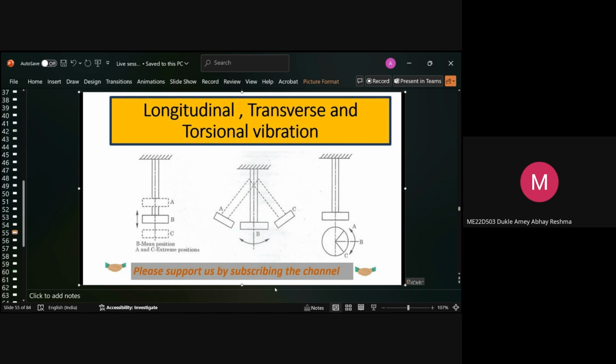When there is a pulling and a change in length, as we saw in the previous question on the stress and strain relation, then it is the longitudinal vibration. When the force is applied and there is a deflection happening, with an angular movement, that is called the transverse vibration.